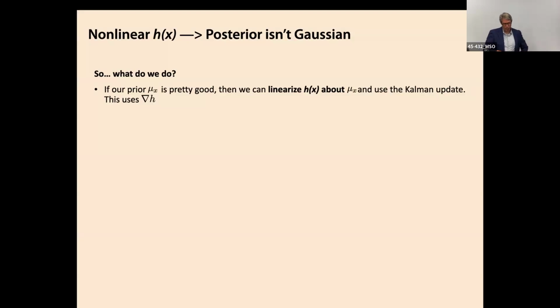So let's imagine, for example, the pressure depends non-linearly on velocity, right? So you could think of Bernoulli, P plus 1/2 rho v squared is a constant, right? So pressure goes quadratically with velocity. And if my flow state is velocity, then pressure is going to depend non-linearly on that. And so that means that H is going to be a nonlinear operator, okay? And I need to deal with that, right?